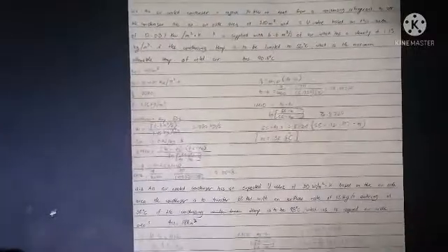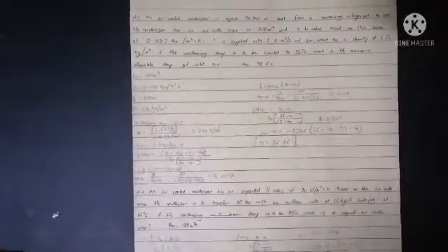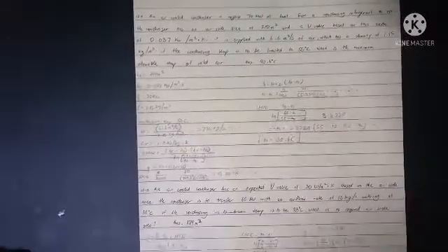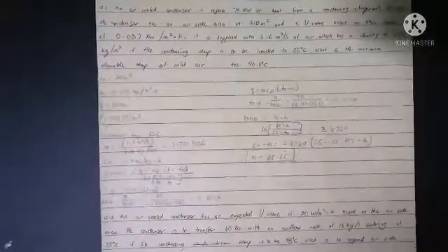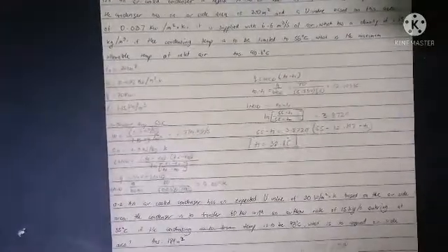And the condensing temperature is 55 degrees Celsius. So W is equal to 6.6 cubic meters per second times 1.15 kilograms per cubic meter, so that is equal to 3.739 kilograms per second. Cp is 1.0 kilojoules per kilogram Kelvin.